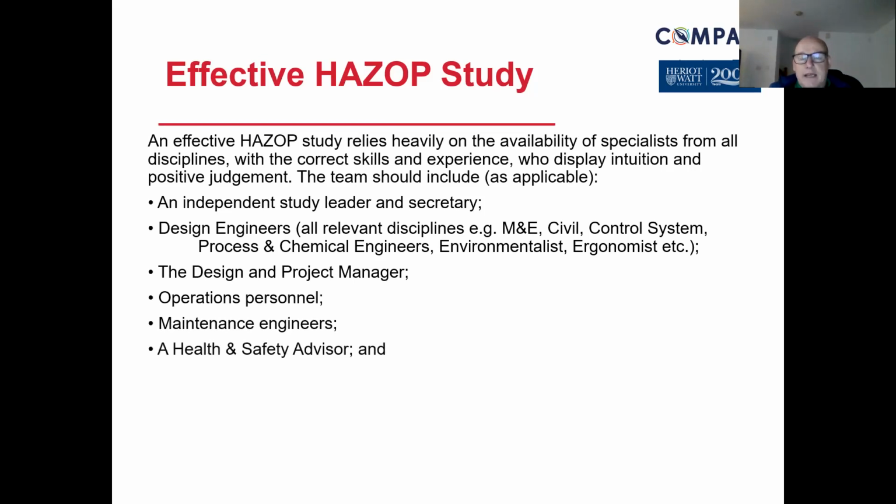Usually, it's kind of like the what-if bit, but often I've seen with HAZOP studies, they forget to bring in the health and safety advisor, the competent person, at their peril in some respects, because you'd hope that someone like yourselves, who are working at a level 7 masters, would understand the legal perspective, but also understand how you interpret safety management systems, and then how they are applied, and then how they're checked, inspections and audits. And those things are important parts of making sure that it's brought within the HAZOP study.